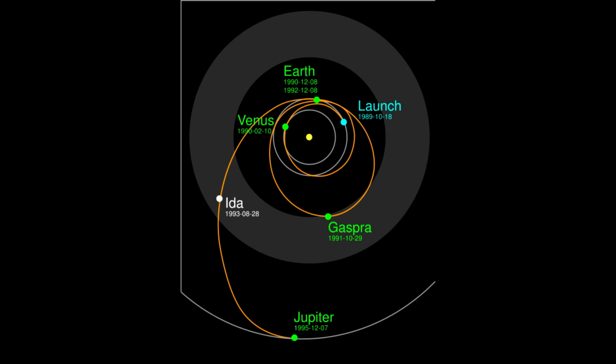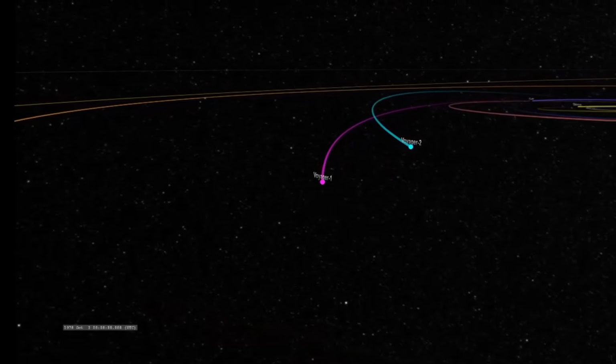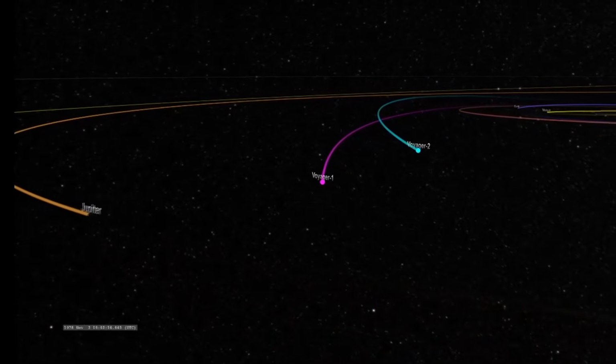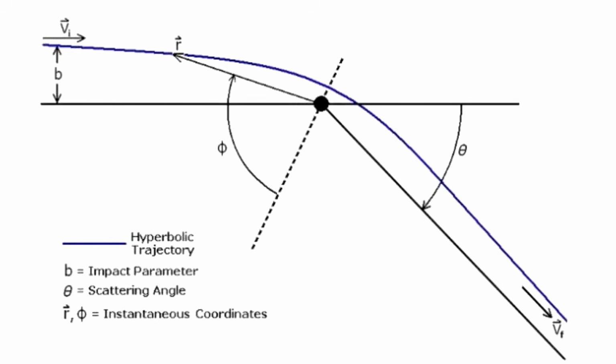And the other thing you'll do is you can calculate the hyperbolic fly past, where you basically assume that you come in from deep space at infinity, follow a hyperbolic trajectory past the planet, and shoot off to infinity. And there's a very simple equation between the velocity you arrive at, which is identical to the velocity you depart at, and the angle through which this is bent.